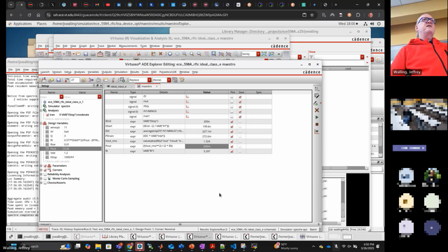There are some non-idealities that we're not accounting for, like the overshoot non-idealities and things like that, which will account for the differences. But anyhow, pretty quick and easy way to design a Class E amplifier. And all these things are really doing exactly what the PSS simulation does underneath. They're just using the calculator function instead of letting PSS do it for us. We're basically looking only at the fundamental. We just ignore every harmonic.